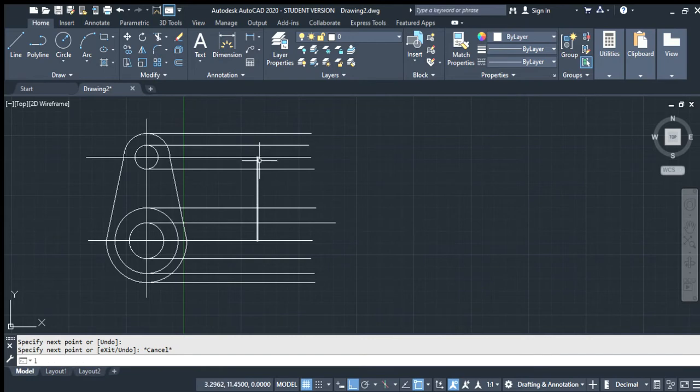So I'm going to go ahead and hit line, go up here, have a random point. Why is that? Oh, that's selecting from midpoint. You could turn that off, I suppose, but we do not necessarily need to. Here's what we'll do. We'll go ahead and delete that one. L for line. We'll redraw the top one, but this time only go enough that we're encompassing all of these, and then we'll finish our line.